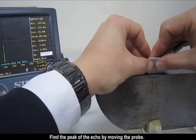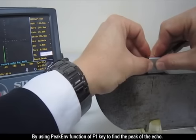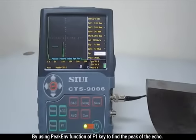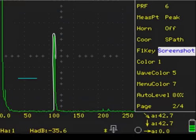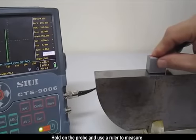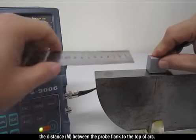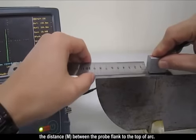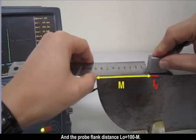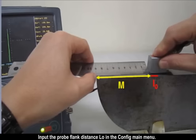Find the peak of the echo by moving the probe. By using peak envelope function of F1 key to find the peak of the echo. Hold on the probe and use the ruler to measure the distance m between the probe front edge to the top of R, and the probe front distance L0 is 100 minus m. Input the probe front distance L0 in the Configure main menu.